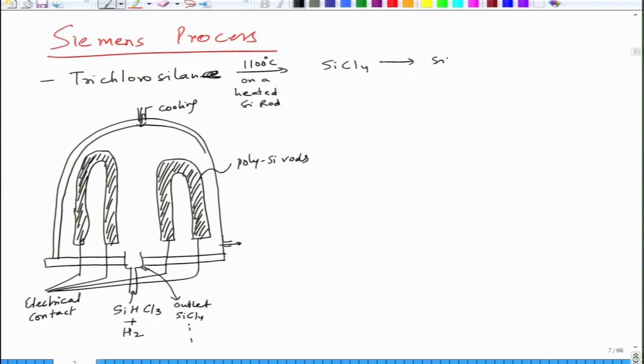So this is a double walled chamber. So this has coolant flowing, and the coolant keeps this cool, okay. So this is coolant. Now in this, the reactions that happen are 2 SiHCl3 makes SiCl4 plus Si plus 2HCl. So it's not a very friendly reaction. You can see that the things that are forming are not very benign, and this happens in multiple stages.